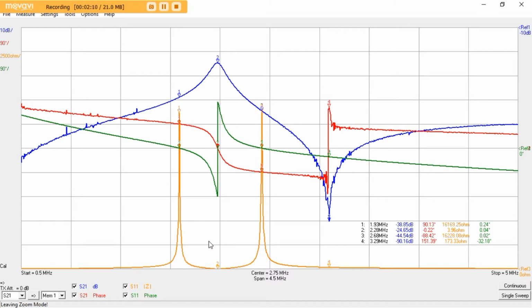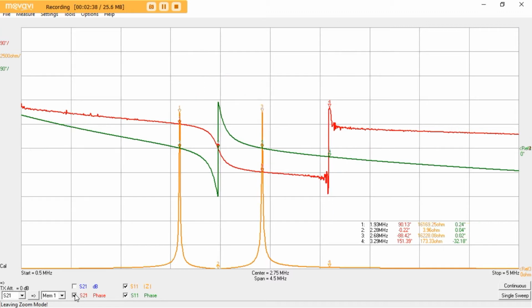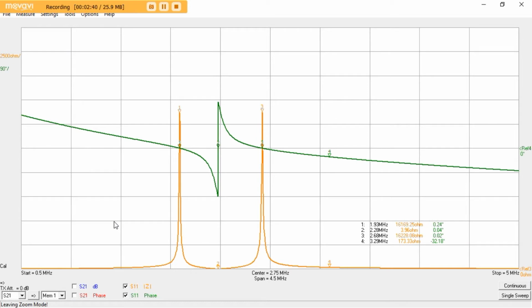Now currently I've got the return wire to the input of the vector network analyzer attached to the plastic ring, as I showed earlier in the video. It's not actually attached directly to the last copper turn at the high end of the secondary coil. So first of all, this is the Z11, the input impedance. I'm not scanning at the moment; I've taken a scan and paused it.